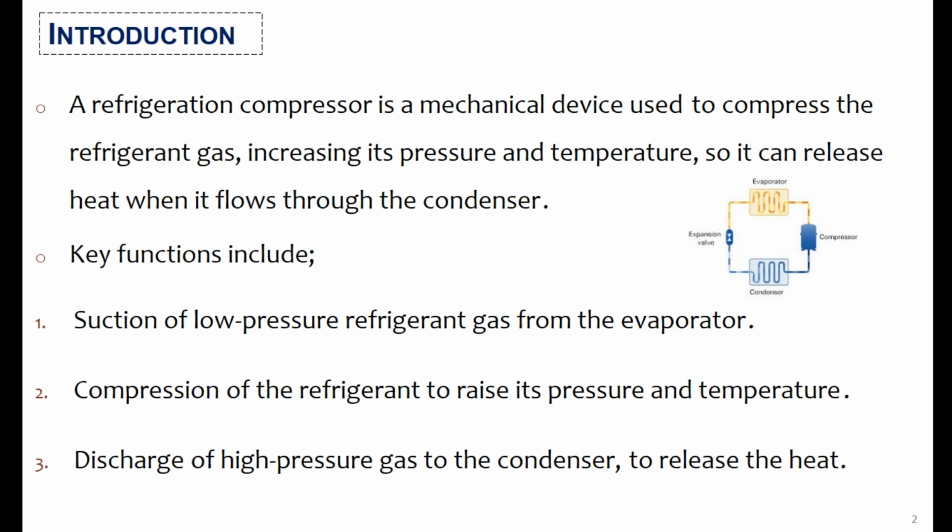The key functions include suction of low pressure refrigerant gas from the evaporator, then compressing it through the compressor to raise its pressure and temperature, and finally discharging this high pressure gas to the condenser to release the heat.